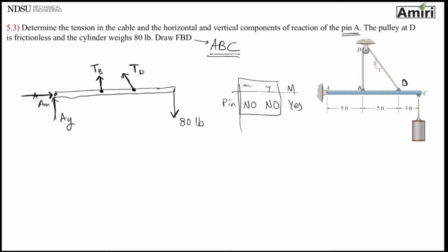But if you look at this pulley system, if you want, you can draw a free body diagram of, oh, I had a point D. Shoot, point D1. There we go. Problem solved. Free body diagram of pulley. Something like this. It's a pin. I like to put an X and Y, dx and dy on a pin all the time. I have TB and I have TD1 going that way.